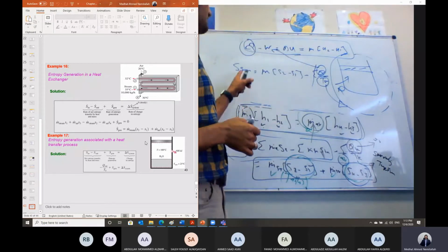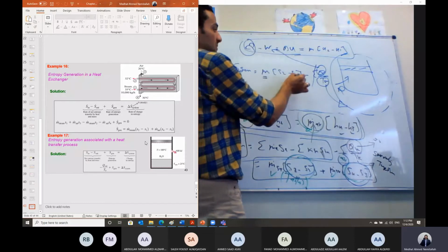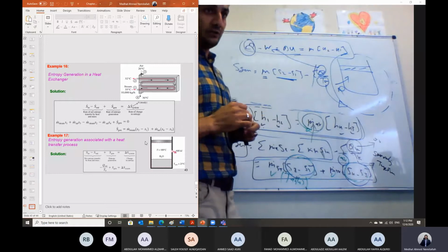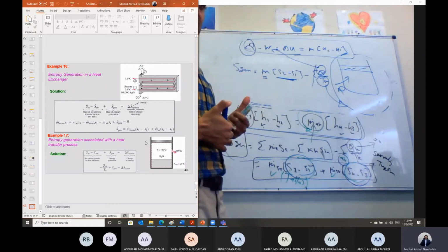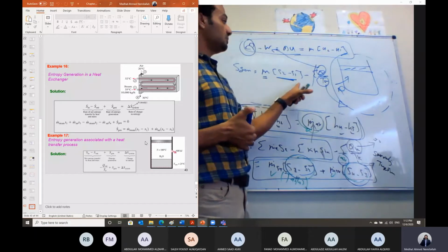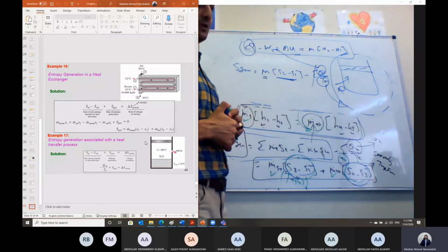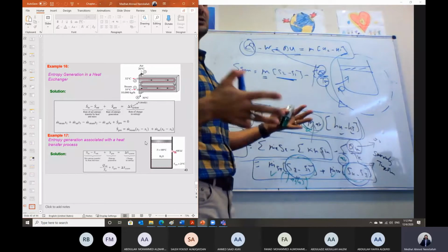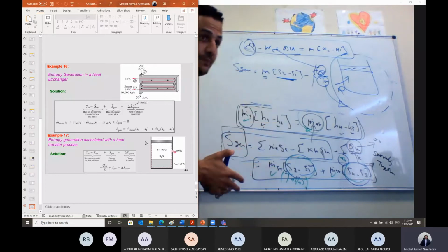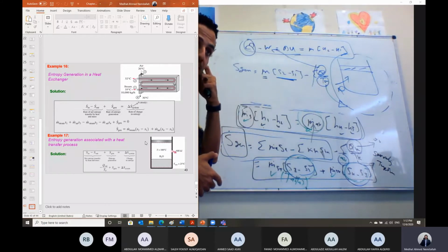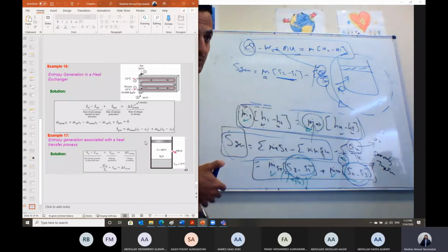of thermodynamics. Then the entropy generation will equal mass multiplied by delta S. And this delta S depends on the working fluid. If it is steam, I will be using the table. If it is refrigerant, you should be given the initial and the final state condition, and also I will be using the table. If it is gas, as we said, or air or any other gas, in this case, I will be following either the constant specific heat analysis, using one of the two equations I have just written, or